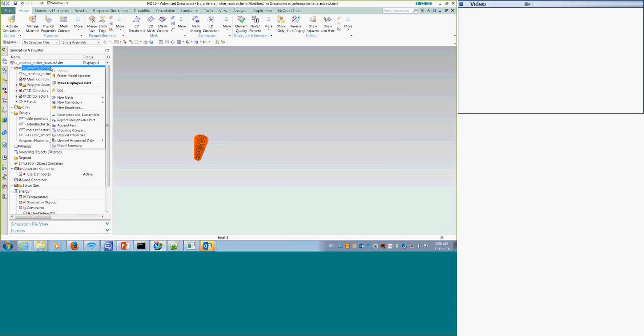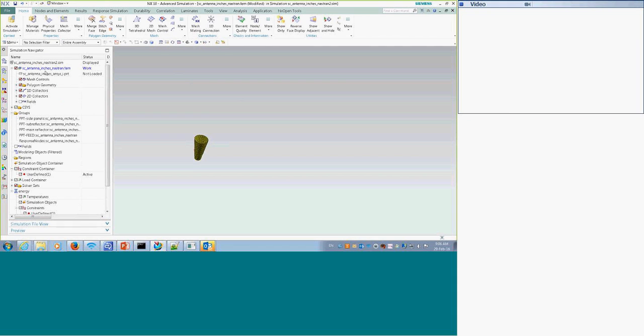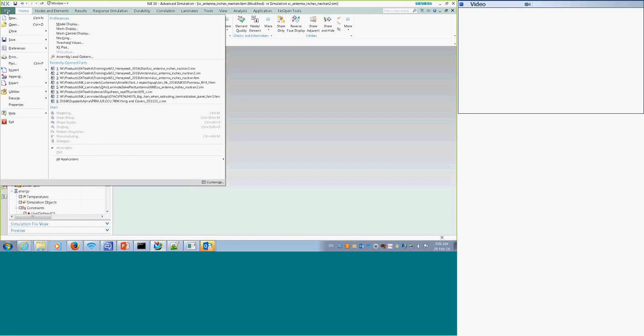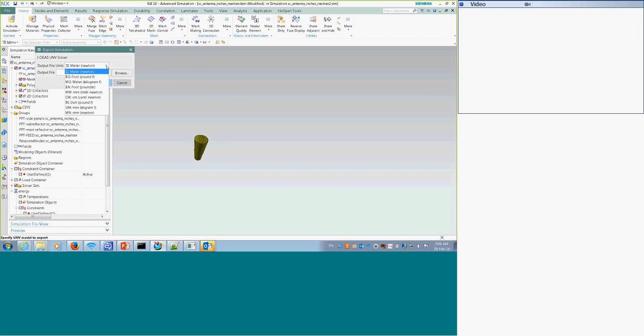I'm going to universal file so I can reuse it by the processor. I'm going to change this. I'm going to edit my FEM and I can change to any solver. I'm going to pick ID as UNV here, the universal file format that we're seeking. So now to universal language and export it. I'm going to go File, Export, Simulation.